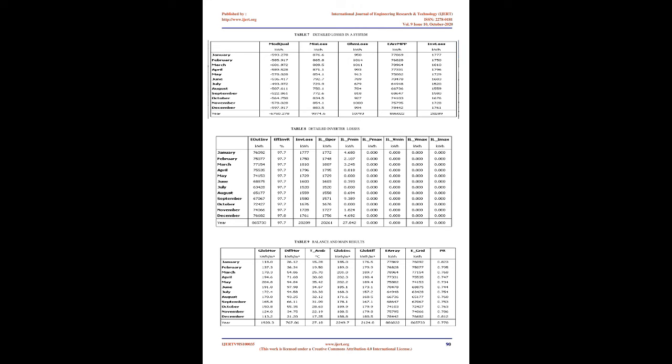4. Soiling loss. Accumulation of dirt and its effect on the system performance is an uncertainty which strongly depends on the environment of the system, raining conditions, etc. Taking into consideration the dust in the desert region, we are taking an approximate value of 3%.